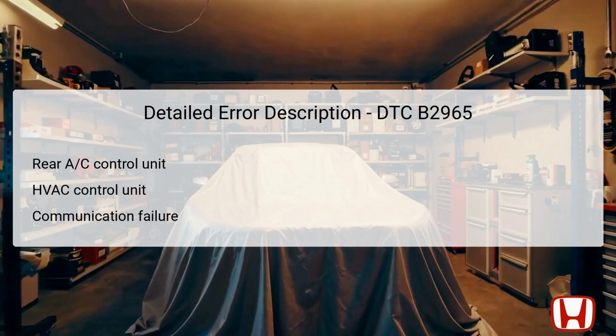The DTC B2965 indicates a communication failure specifically linked to the rear AC control unit. The affected components are the rear AC control unit, which is responsible for controlling the air conditioning settings for passengers sitting in the back seats, and the HVAC control unit, which manages the overall heating and air conditioning in the vehicle. These units transmit signals back and forth, ensuring that the desired temperature settings are met conveniently by rear passengers.